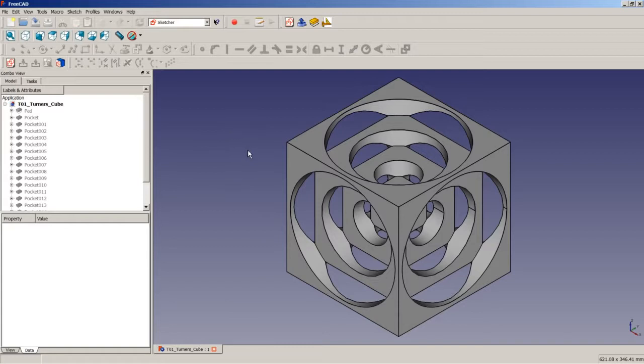And so some users asked one of the first obvious questions: is there a way to duplicate or reuse the sketches to get a more efficient model? Of course, this is possible. We learned during the lessons that you could reuse the sketches by copying them, for example, to the clipboard and inserting them somewhere else. And you can also reorient the sketches and attach them to other faces.